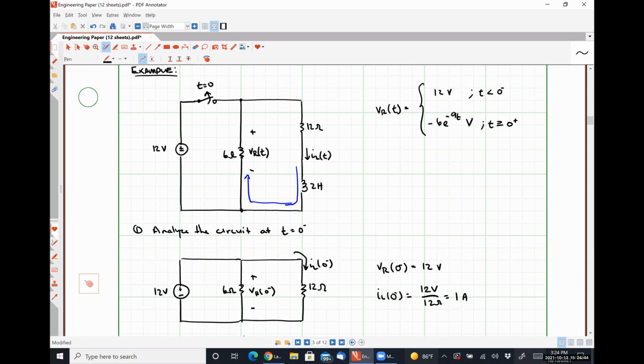Then Ohm's law tells us that the voltage drop across the resistor will also decay exponentially. And Kirchhoff's voltage law then tells us that the voltage drop over the inductor will decay exponentially. So what we're going to see in these transient analysis problems is that if one thing behaves with this exponential decay, everything behaves with this exponential decay in order to satisfy Kirchhoff's voltage law, Kirchhoff's current law, and Ohm's law.